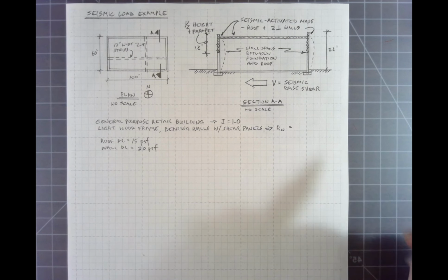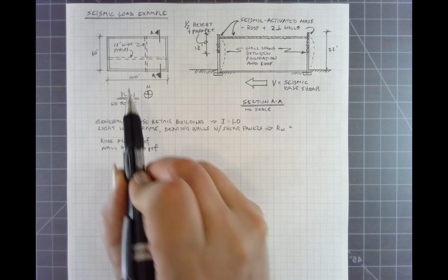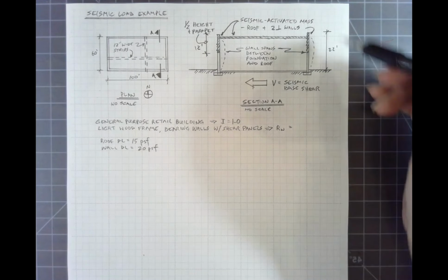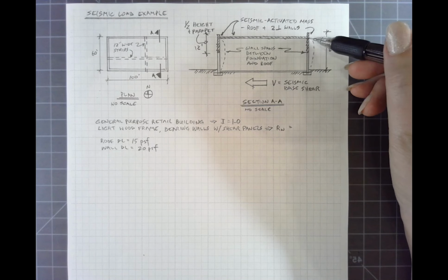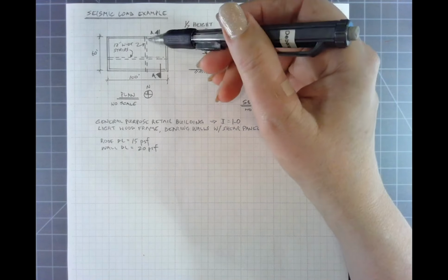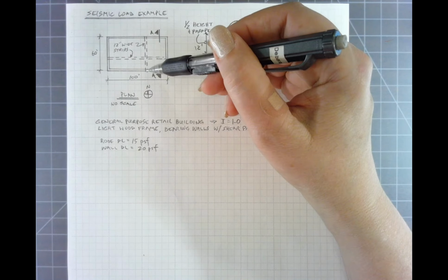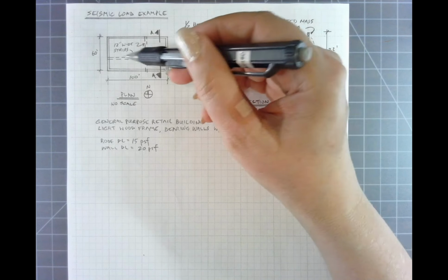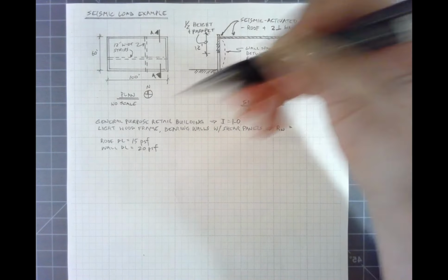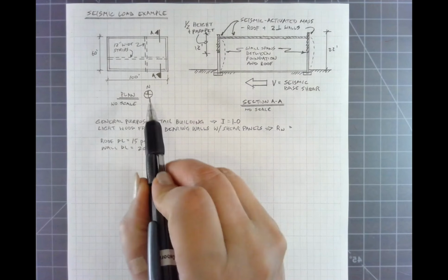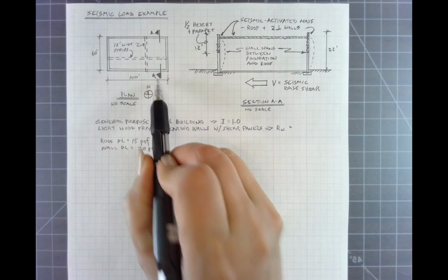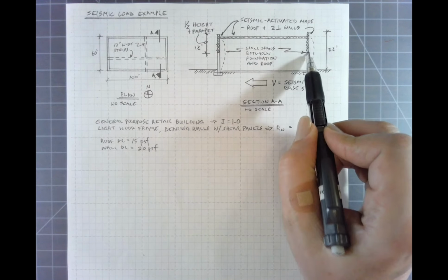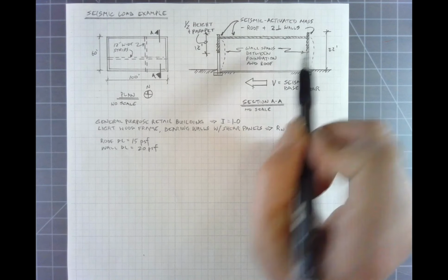All right, so here's our building in diagrammatic form. 100 feet long, 60 feet deep, 22 feet tall to the parapet, 20 feet up to the roof line. So again, we are splitting this up into 12-inch segments, both in the north-south direction. North is going up on this page, and also in the east-west direction. So we need to calculate loads in both directions. So a typical section through the building here, section A. This is the C shape that was shown on the computer model. That's the load that we actually want to calculate.